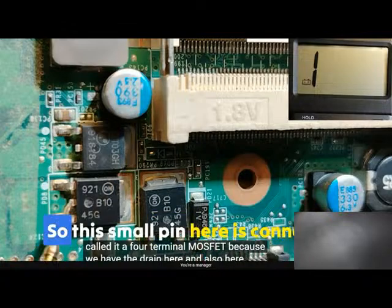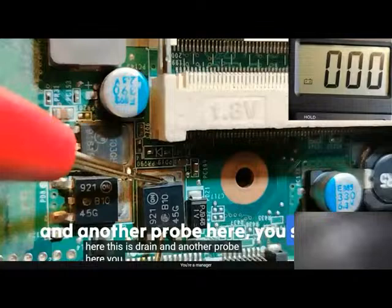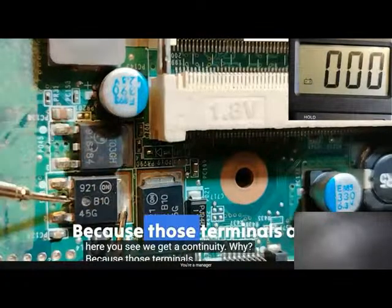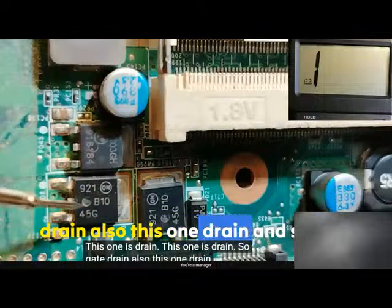So this small pin here is connected to this pin. We can even check: if I put one probe here, this is drain, and another probe here, you see we get continuity. Why? Because those terminals are connected. This one is drain, this one is drain. So gate, drain, also this one drain, and source.